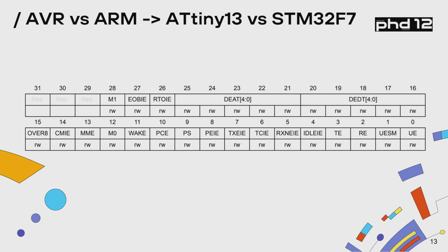So, for example, a video camera will have its own SoC, and a couple of vendors will be using this SoC, but others won't. So you will need to read the separate specs for it. If you simply load the data into an ARM interface in a disassembler or a decompiler, you can see what's happening at the register level, where most of the fields will be occupied, and you will have to toggle the bits inside this register many times, but you still will struggle to learn what these particular bits are doing.